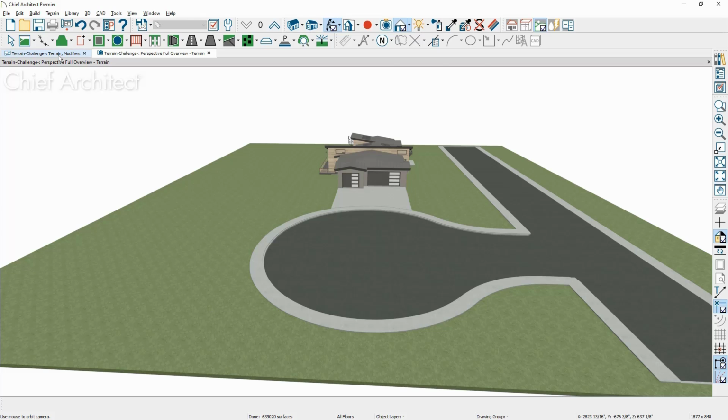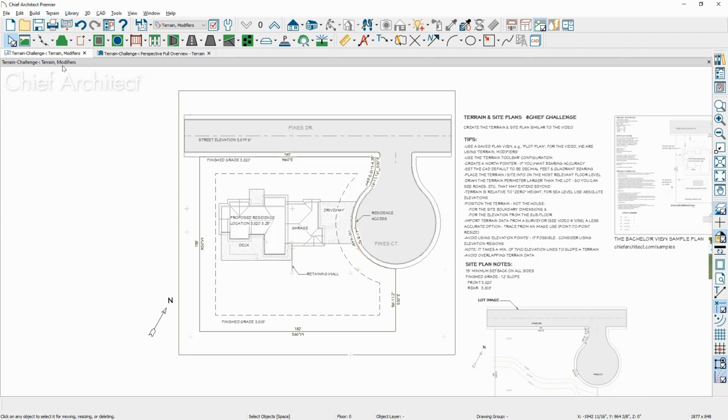The easiest way to slope your terrain is to use the terrain line tool. As I began the video, I try to discourage using terrain points or elevation points. They can get detailed and can be complex to work with. You might think about using the elevation line and elevation splines. I prefer to use the elevation regions. I'm going to begin by just using an elevation line.